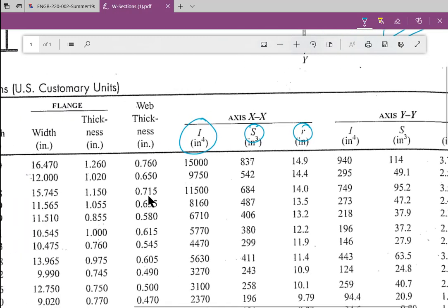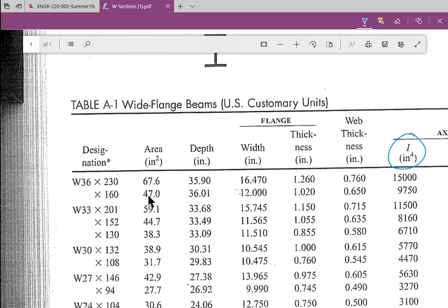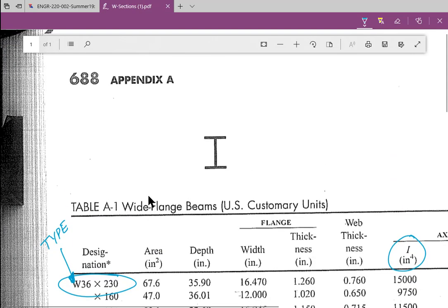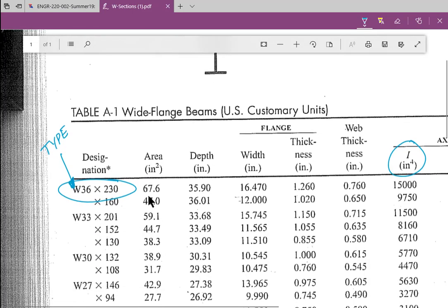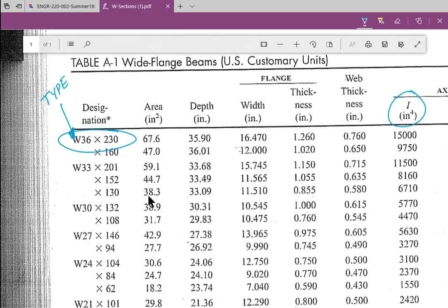So that beam, let's look at its name. These are the beam designations. Those are the names, and there are three parts. You've got the type of beam. Most of them make a lot of sense, like C looks like the capital letter C. T looks like a capital T. I is an I. In our charts, the ones that we have are W's. So they're actually wide flanged I-beams. And they give you a picture, so you should be able to see what the thing looks like. But the W is wide flanged I-beam.